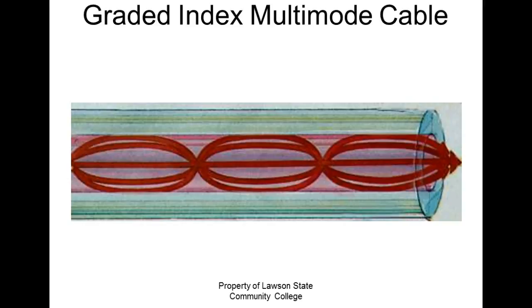The most popular multimode cable is, so y'all know what multimode means. What is a mode? Well, a mode is a path the light takes down through the core. If we say single mode, it's got how many paths? One. If we say multimode, we know it's got more than one, right? If we say stepped index, that means that sucker's just stepping down the sides, right? Graded index means we're going to do what? We're going to curve it. We're going to deliberately curve it through the core. So the core actually has different glasses in there.